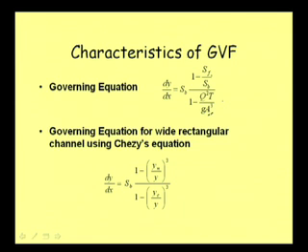So, and that we can achieve by considering the channel to be a wide rectangular channel, and we did discuss in the last class the governing equation for a wide rectangular channel. Using Chezy's equation as the resistance formula, we could get the equation in this form, that is dy/dx is equal to SB into (1 minus (yn by y) whole cube) divided by (1 minus (yc by y) whole cube), where